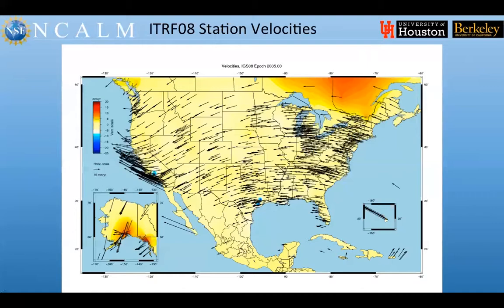We will use GPS in the project site, but we will tie them to local PBO or core stations, and we will use the date of the survey as the reference epoch. So if it was January 1st, 2014, the reference epoch would be 2014.0, basically. If we then came back and did the same thing in 2018, on June 1st, the reference epoch would be 2018.5, or halfway through the year.